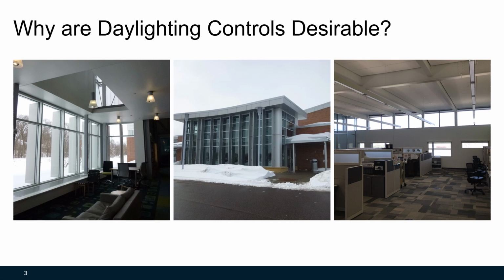We increase energy savings by optimizing automatic control of electric lighting, which also reduces the risk of creating glary, overlit spaces by continuously adjusting electric lights to maintain proper illumination. It was previously more challenging and expensive to control and dim fluorescent lighting, but with the increasing adoption of LED lighting, many of these challenges have been mitigated.